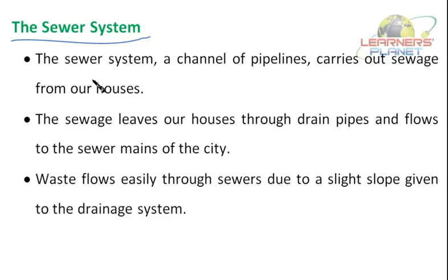These local sewers transport the wastewater into many miles of large sewers, and the interceptor sewers, ranging from some inches to some feet in diameter, carry the regional wastewater to large treatment plants. Though most of the wastewater flows by gravity, some low-lying areas also require pumping. In this way the sewer system works.